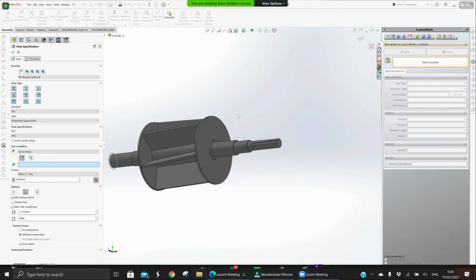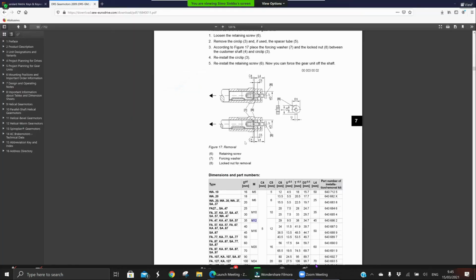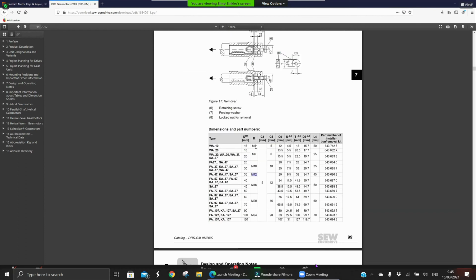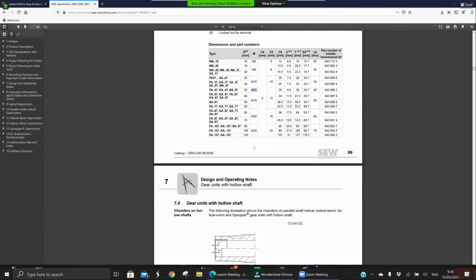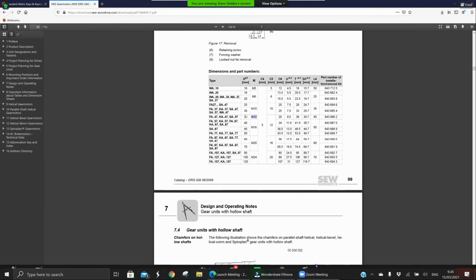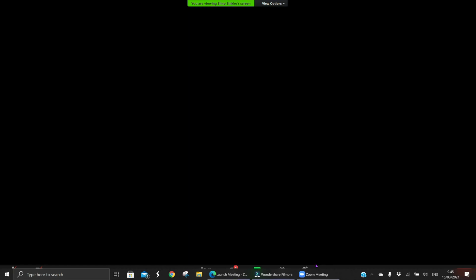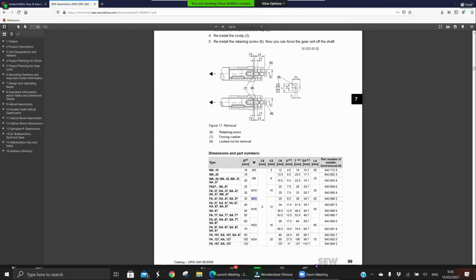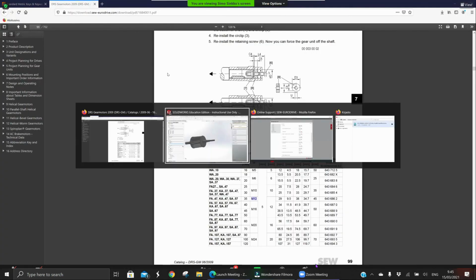And how deep it should be, well, we can estimate it, or was there any information given for that one? Not directly in this table. So let's just estimate. Okay, we can see that the length of the bolt L4 is 45 millimeters, so it makes sense that we have at least 50 millimeters threads there.